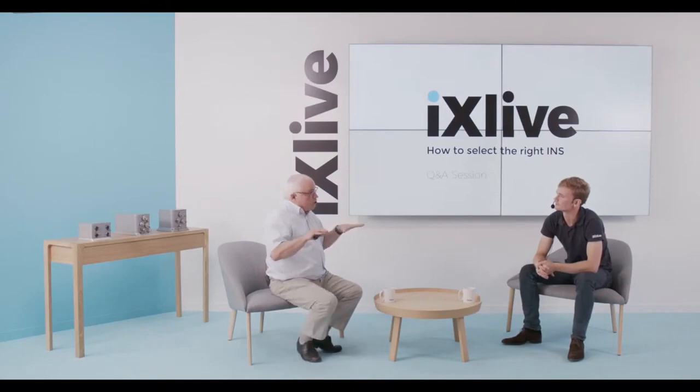So knowing the horizontal plane, then we measure the three components of the measurement of the gyros. When the gyro is not moving on the vehicle, the measurements of the gyros are the three components of the Earth rotation rate, only because the rotation rate of the gyro with respect to Earth is 0.